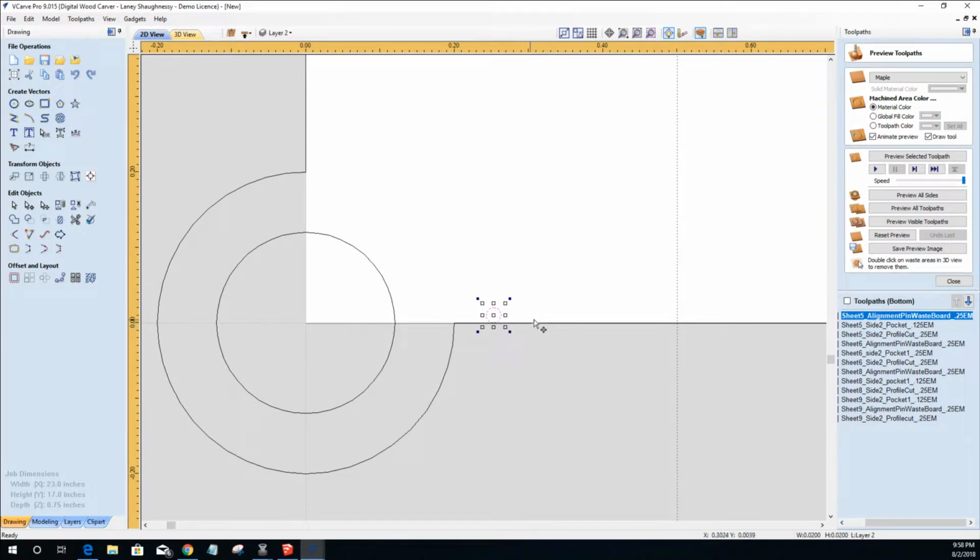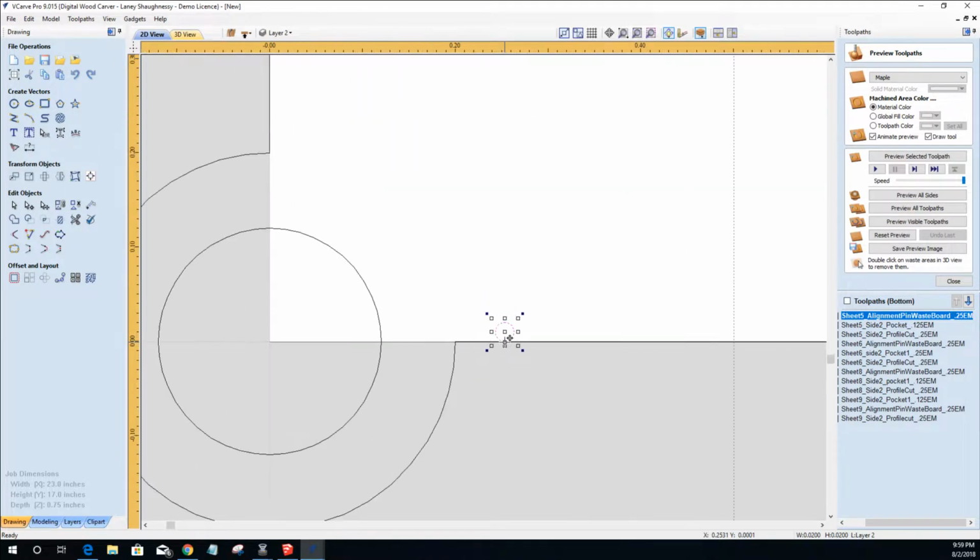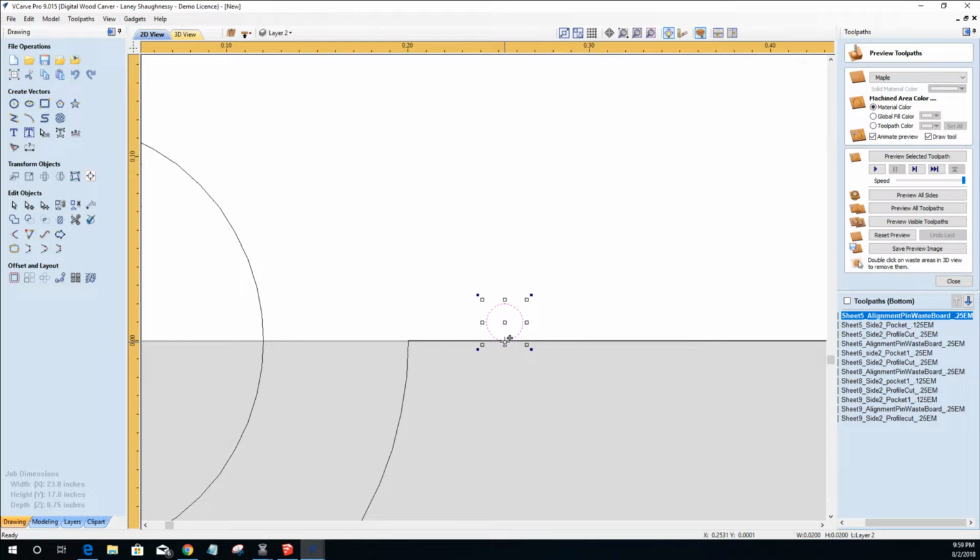Okay? This fence, my bit, edge, I want my center, right? But if I'm touching my edge up against it, what's my diameter? If it's a 1/4 inch, then I'm 1/8 of an inch. I'm right now sitting at positive 0.125, so I type in positive 0.125 in my y-axis. That way when I bring it to 0, boom, it moves it down there, right?